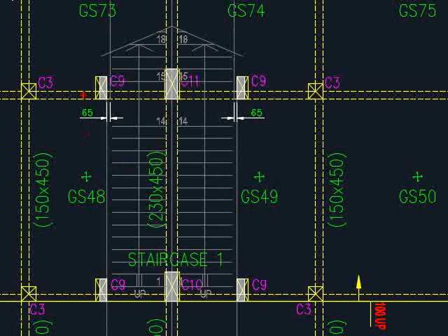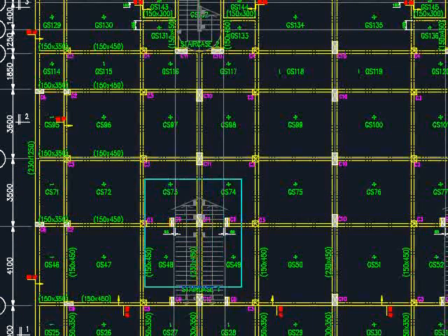In the case that there is an offset of a certain structural element from the grid line, the offset needs to be clearly indicated. And remember to number the staircase for easy reference, which in this case there are two types of staircase here. To avoid confusion, you give proper names for the staircase.